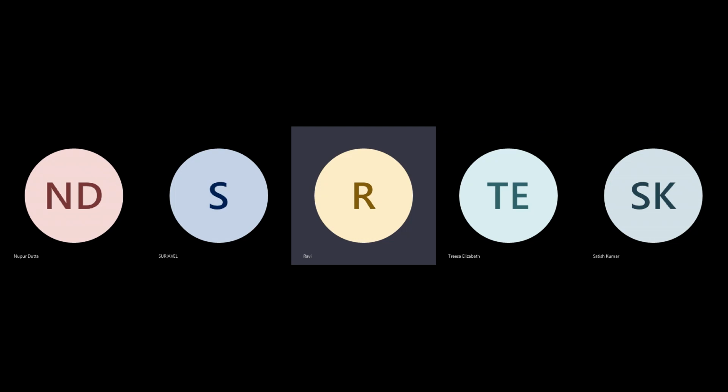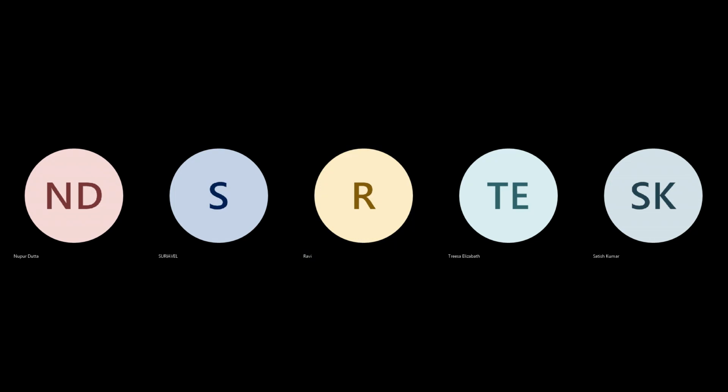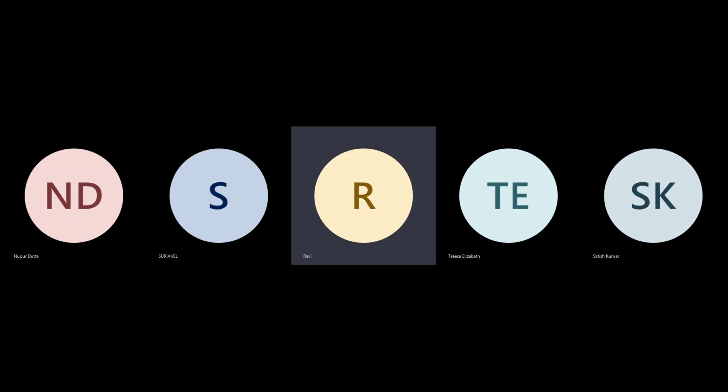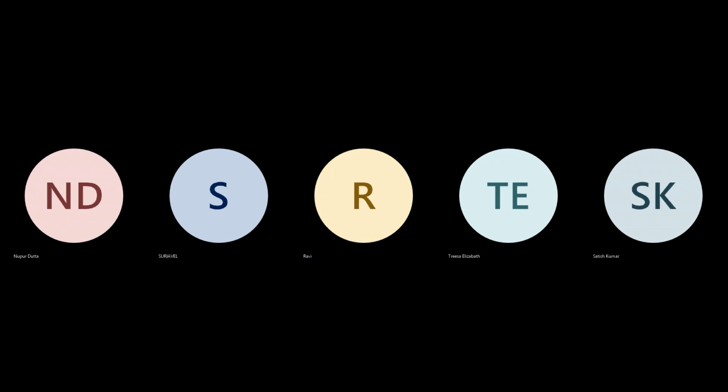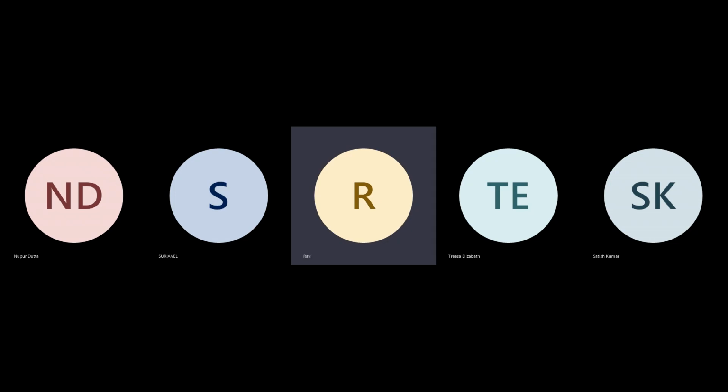Placement, you should not run like you are running in the final iteration. You are doing your initial trials. For the initial trials, your idea should be that placement runs fast, quickly. It should tell you where the congestion is. It will give you the quality of timing. I should be able to get as much information for my floor plan as possible. That should be your goal.